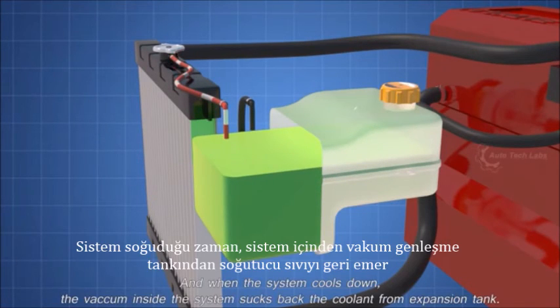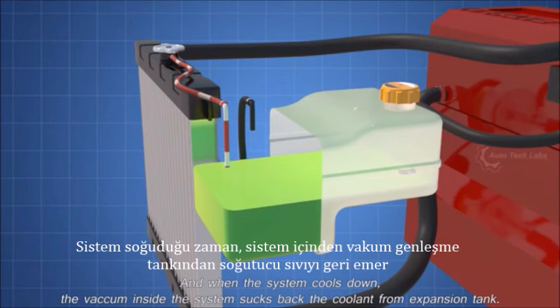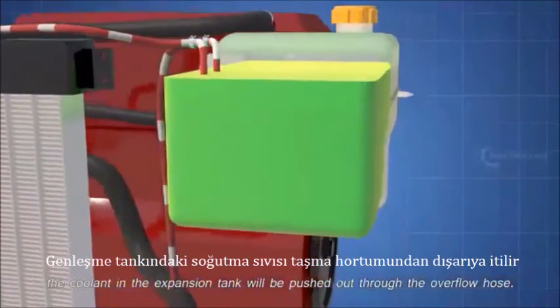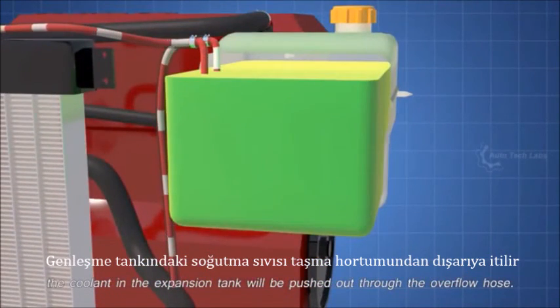And when the system cools down, the vacuum inside the system sucks back the coolant from the expansion tank. In case there is too much pressure build-up in the system, due to trapped air or other failures, the coolant in the expansion tank will be pushed out through the overflow hose.